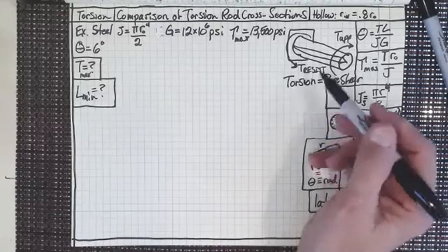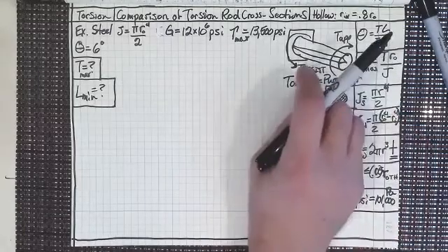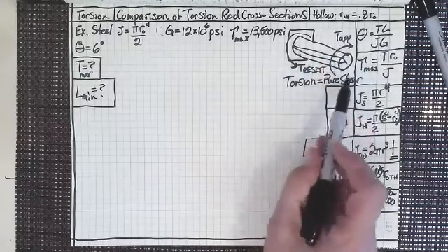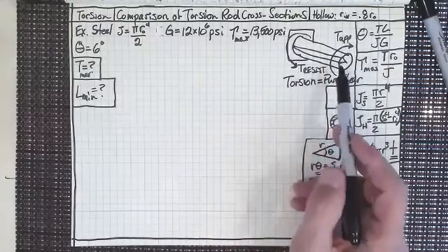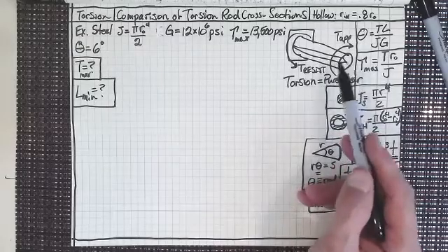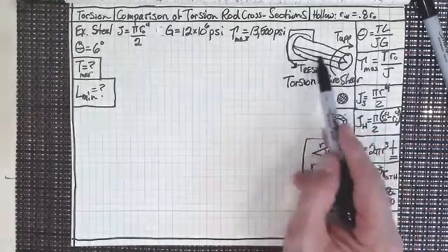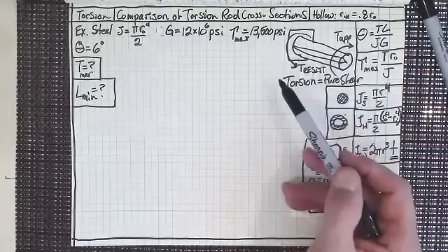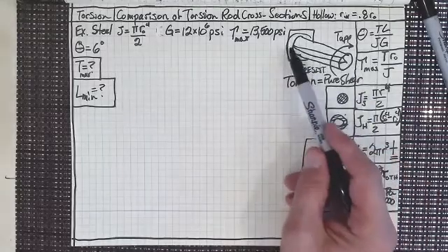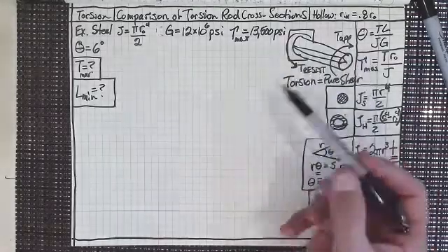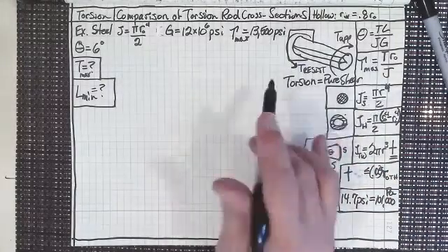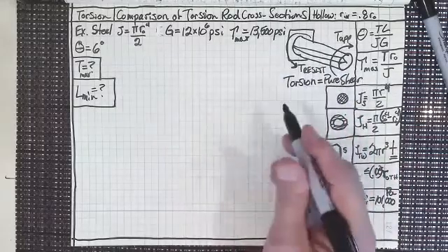I'm probably saying, oh, that sounds like a luxury on a truck. Yes, but it wasn't a luxury in a station wagon, was it? And that's what they had on every station wagon in 1980, 1990. They had a torsion rod back there. The problem was that sometimes after a lot of repetition, or due to corrosion, the torsion rod would break. Then you'd have to lift that whole tailgate by yourself. But I would think that they are putting this in some type of truck so that it'd be easier to lift the tailgate. Anyway, that's what we want.